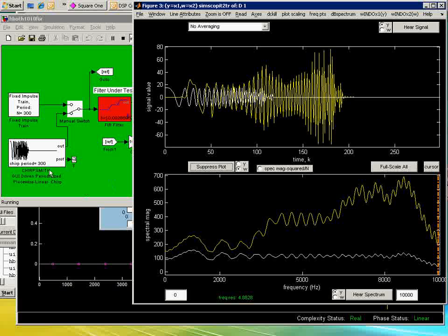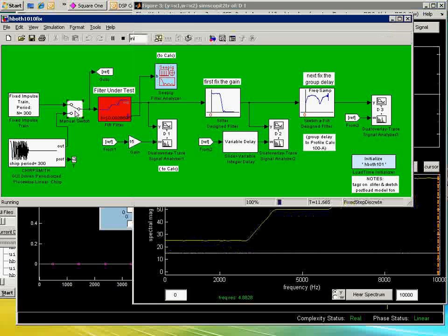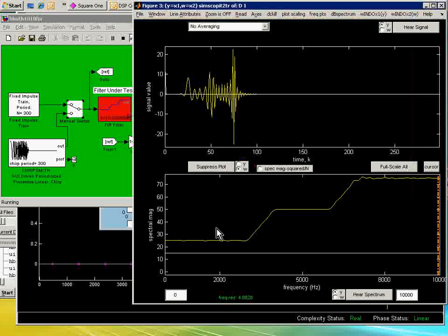Now, if we were to make any headway, it's very useful to do an impulse test on this, and so we do. This is what we've got coming in now. The impulse you can just about see at the left-hand side in white. Very much spread out. Interesting little structural elements of this thing you could probably imagine. But the important thing is that this flat spectrum of the incoming impulse has been rolled up to these three different plateaus here.